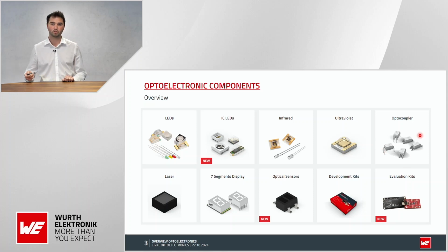And we have optocouplers. They are a little bit special. They don't emit light. They have just an infrared LED inside and also an infrared detector on the other side inside the package. I will get more into this later, how this is built up. Basically it's an infrared LED and a phototransistor inside one package, just that the light doesn't come out of the package.